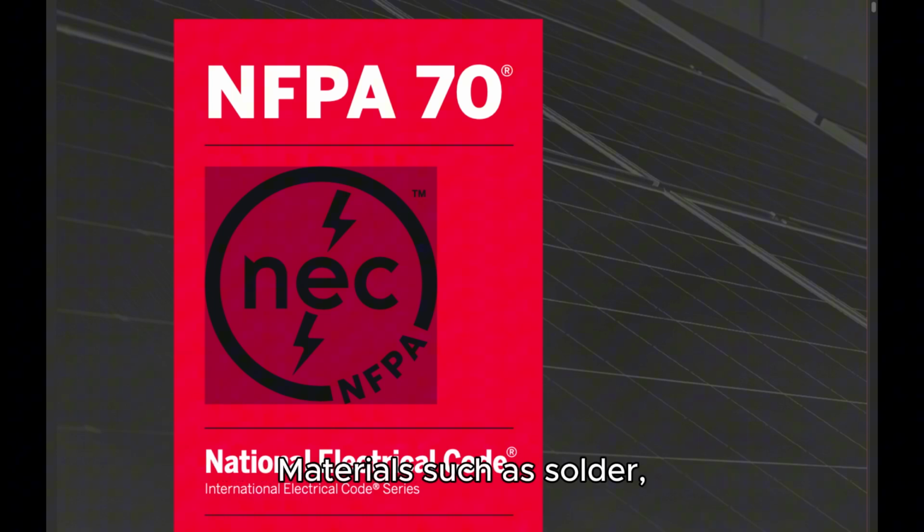Materials such as solder, fluxes, inhibitors, and compounds, where employed, shall be suitable for the use and shall be of a type that will not adversely affect the conductors, installation, or equipment. Connectors and terminals for conductors more finely stranded than Class B and Class C stranding, as shown in Chapter 9, Table 10, shall be identified for the specific conductor class or classes.